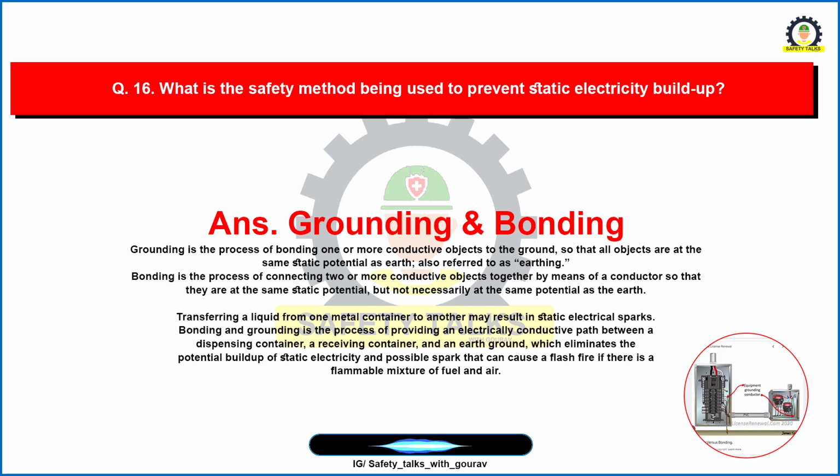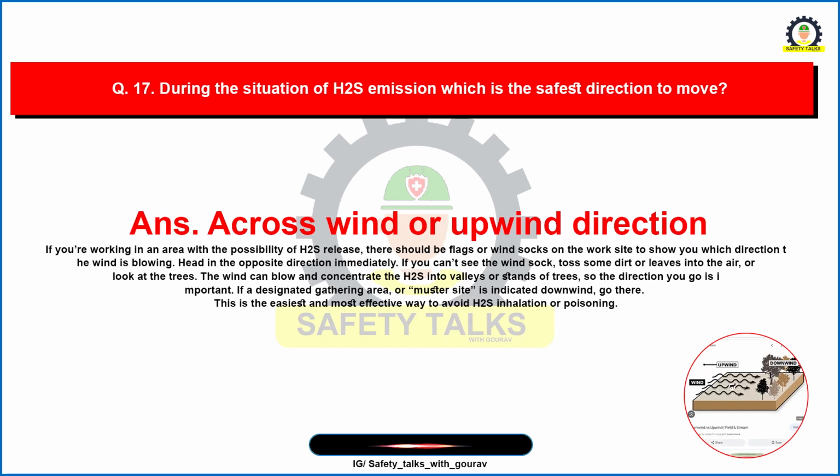Okay, now move on to the next question. Next question goes like, during the situation of H2S emission, which is the safest direction to move? During the situation of hydrogen sulfide emission, which is the safest direction to move? So the answer will be crosswind or upwind direction.